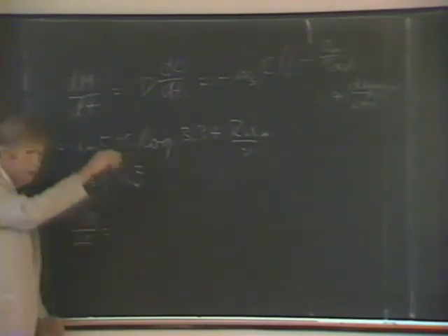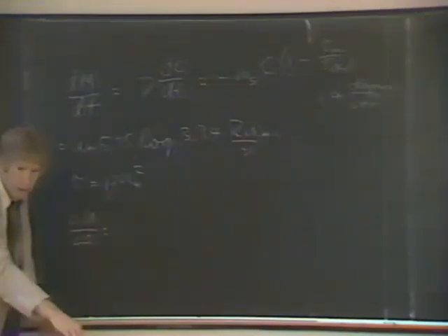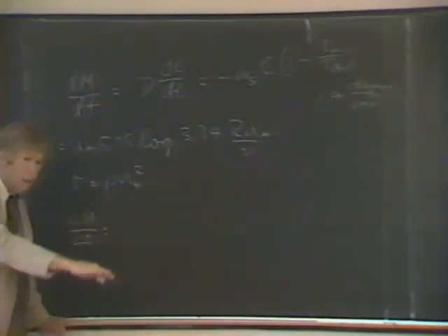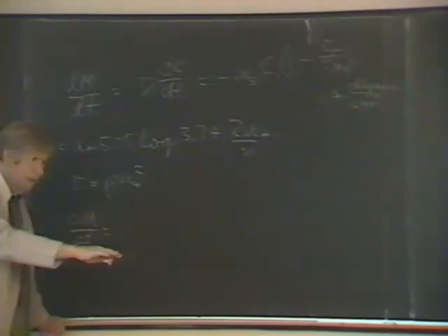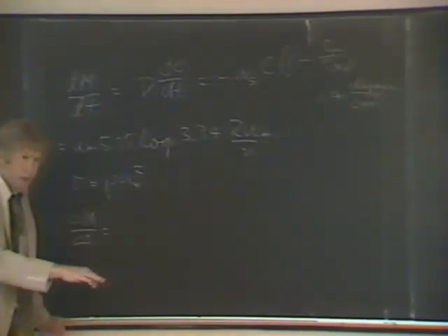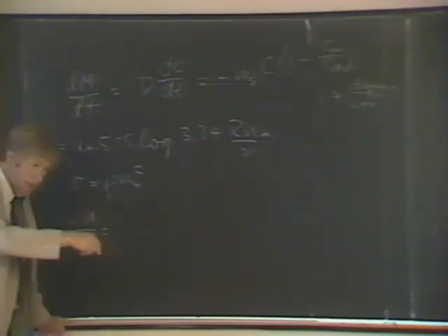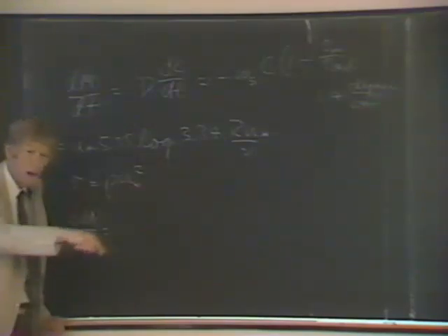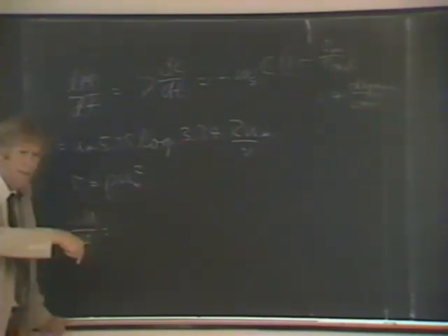So that's the amount of solid particles that settle to the bed. Now, to calculate the change in elevation of the bed, you need to know what that mass of particles does to the volume of 1 square unit area of bed.